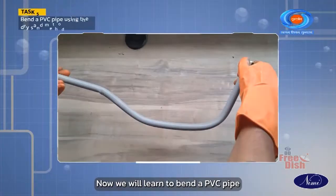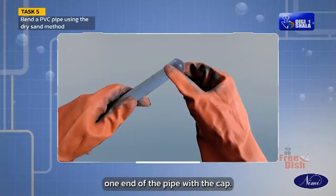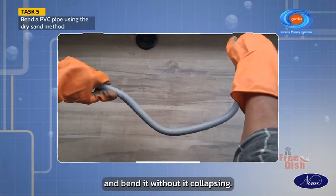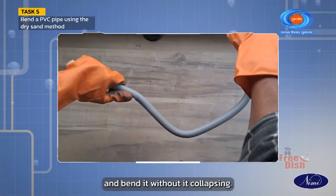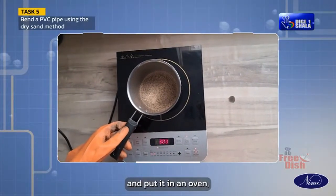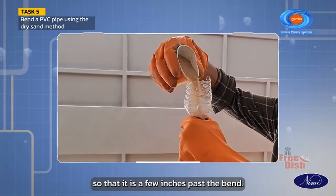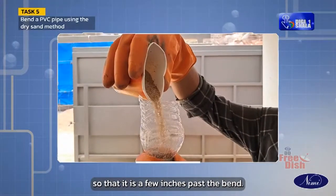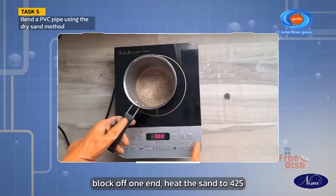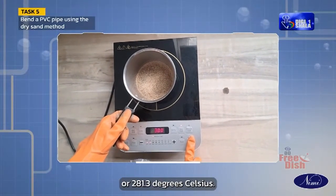Now, we will learn to bend a PVC pipe using the dry sand method. Cover one end of the pipe with a cap. Use hot sand to fill the pipe and bend it without it collapsing. For that, pour the sand into a dish and put it in an oven. Fill the pipe with sand so that it is a few inches past the bend block of one end. Heat the sand to 425 degrees Fahrenheit or 281.3 degrees Celsius.